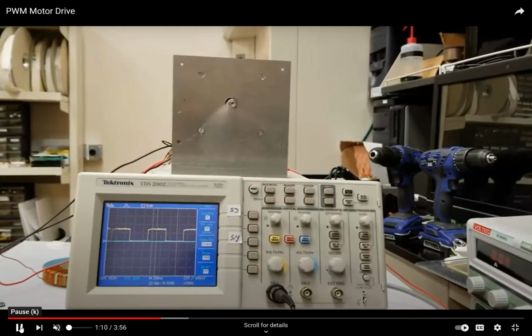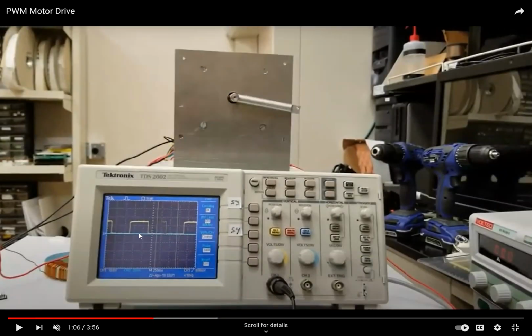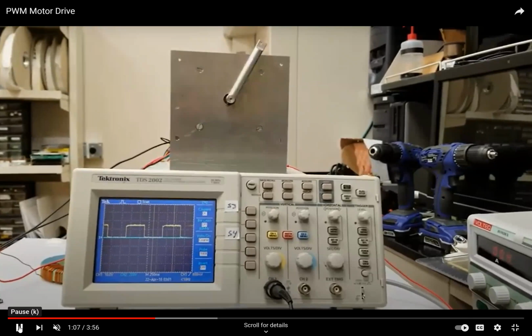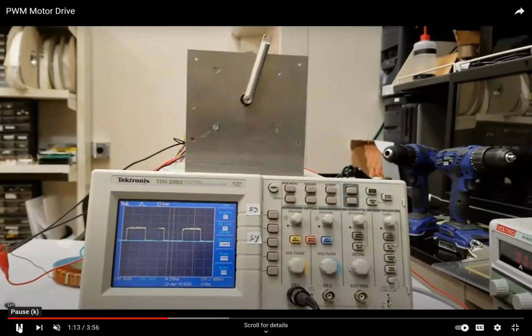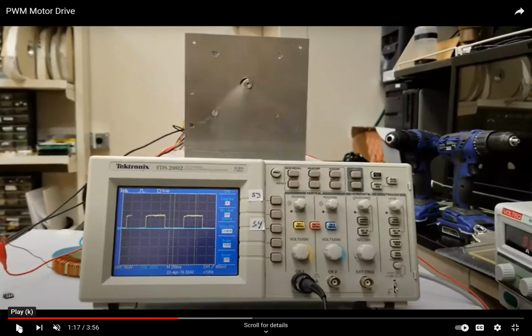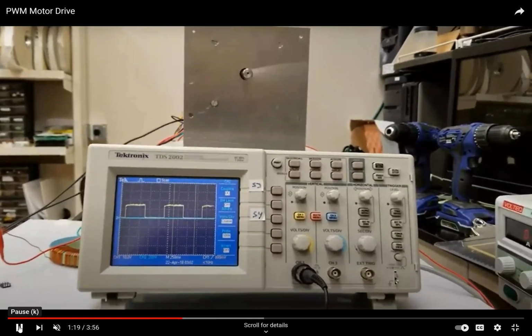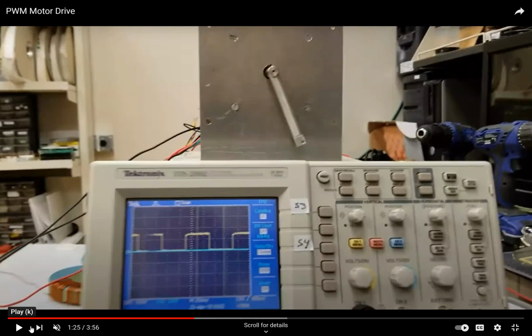So what I have is, notice what's going on here is I've got a series of pulses on that oscilloscope. And what I see is the motor spins and stops and spins and stops. Now, let's say I want it to spin continuously, which is what I want it to do. So what should I do to make it spin continuously? Well, I could make this input constant. That would work. The other thing I could do is speed it up. So let's speed it up.